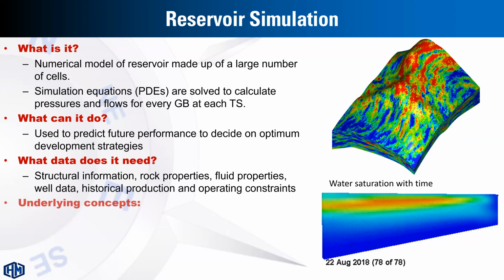The principle for this is the mass balance to solve the simulation equation across one grid block or one grid cell. Darcy's law is used to characterize the fluid flow across the porous media.